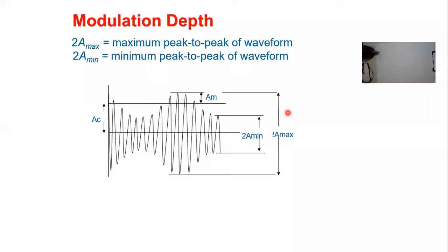Again, in another way, sometimes we call this the modulation, but it's just a different terminology. I believe you already know this. This is the maximum of the signal, and this is the minimum of the signal. We already investigated these two conditions, Ac(1 + k m(t)) and Ac(1 - k m(t)). So this is the minimum, and this is the maximum, and we call this the modulation depth.